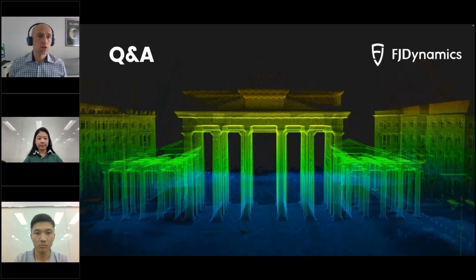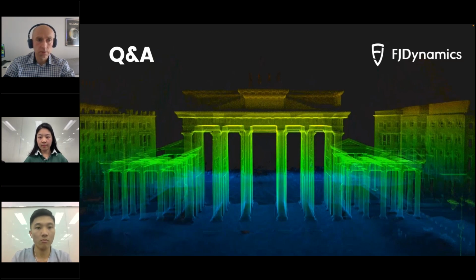You can use recorded control points, even if they are not measured with a total station, but it helps you to stitch two scans together, but it won't transport your scan to the coordinate system. So if you are accustomed to using a total station, just use it. You will get better results, better control of your work, especially if the work demands high accuracy.